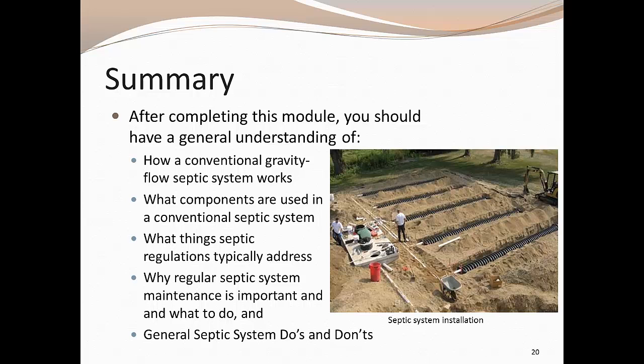By following a few simple suggestions and actively caring for your septic system, you will ensure your system will continue to function properly throughout its design life. Good practices can be as simple as regular inspections, practicing water conservation, limiting the use of harsh chemicals and cleaners, and avoiding compacting the soil above the soil treatment area.